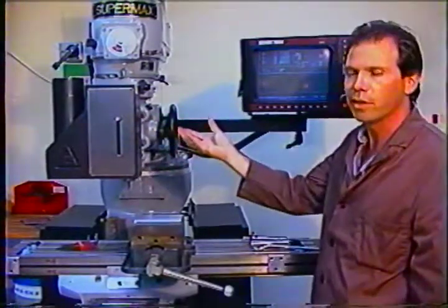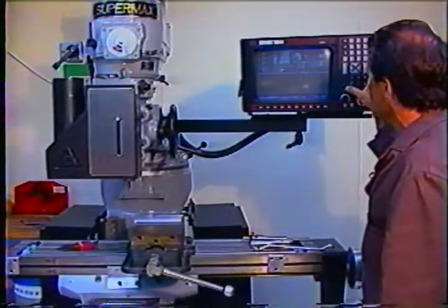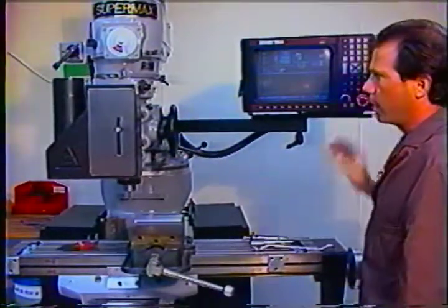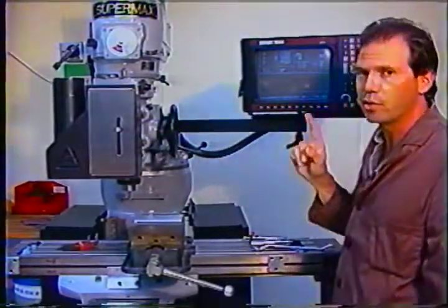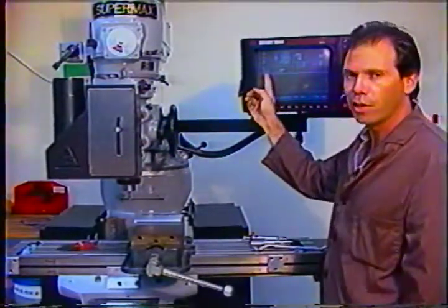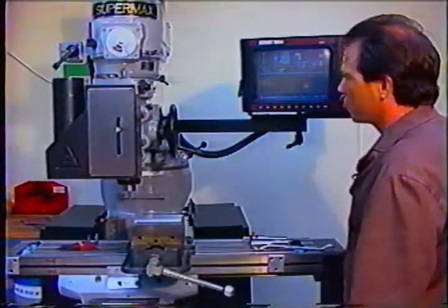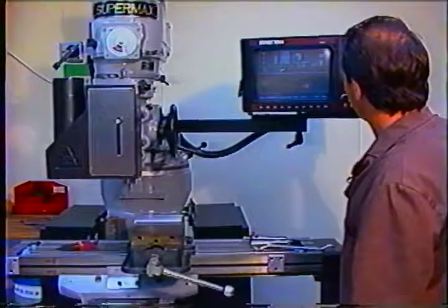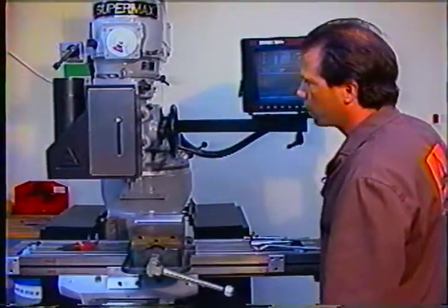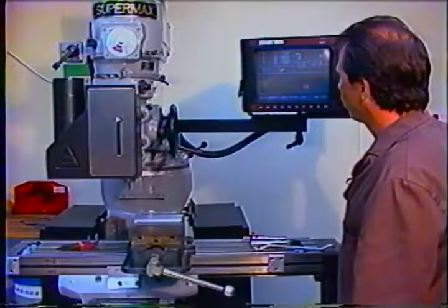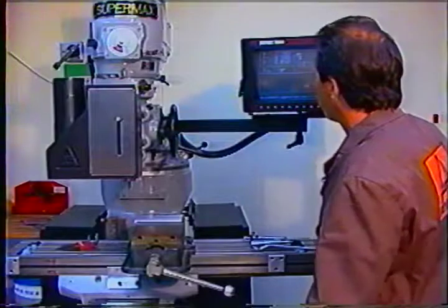It's nearly all the way up to the limit switch. If it was not, let's say that it was down that far, we could set a new Z home position. Again, and most importantly, first of all, we note that tool 0 is active. Now we can set our home position. I can jog the quill up carefully until I'm up near the top of the travel. And I can see by the pointer here that I'm nearly there.